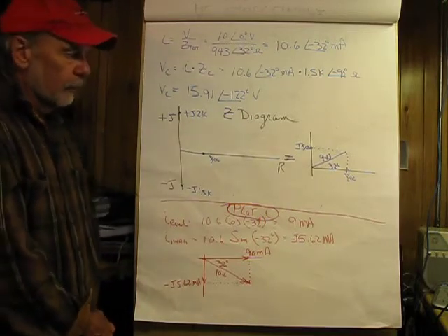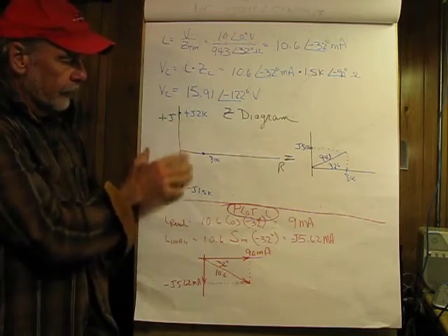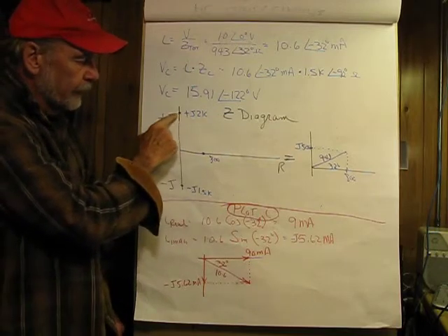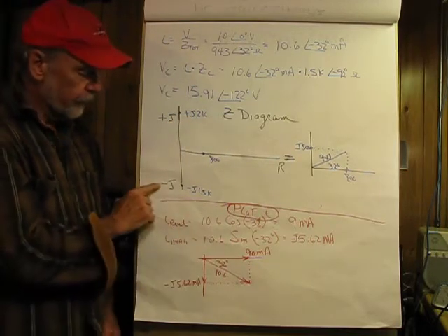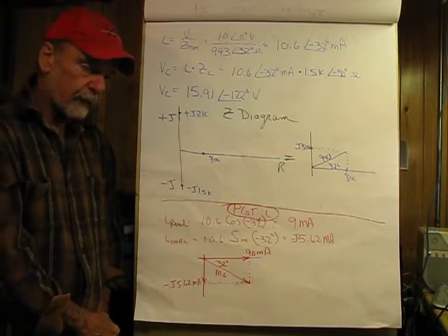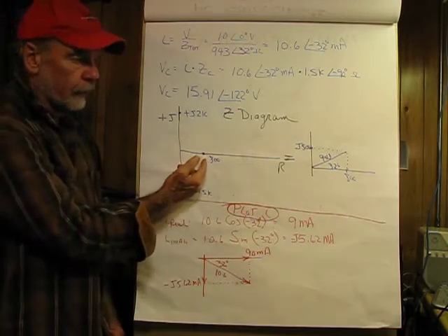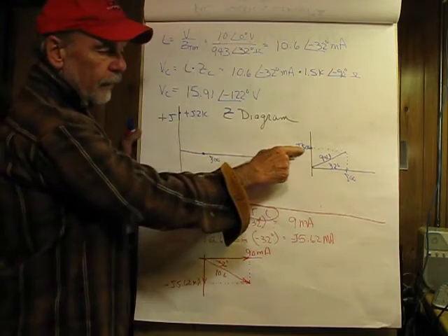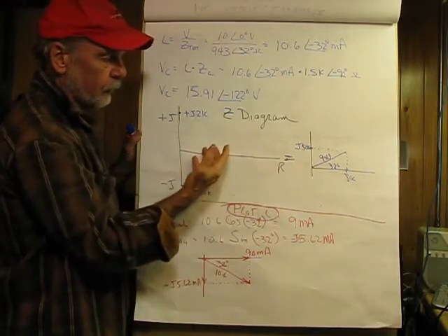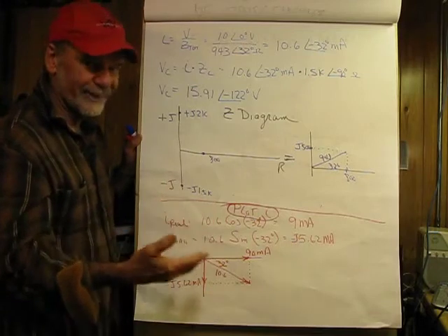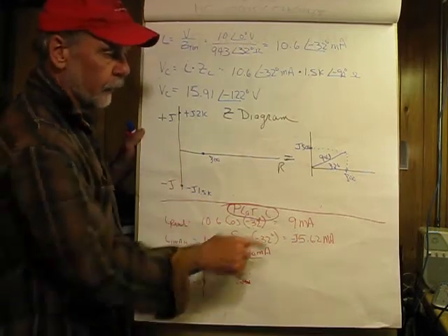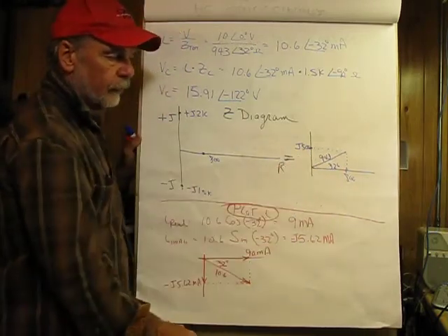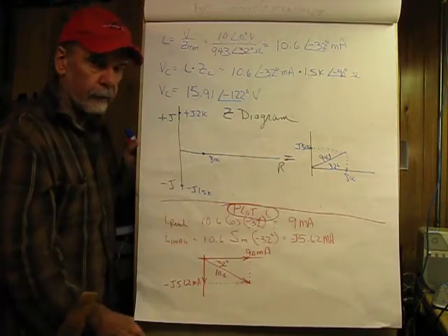So if we look at a Z diagram of this, an impedance diagram, as we're going to see again, this is just a little bit clearer than what I had on the other page. The inductive reactance is sitting up here at j2K, the capacitive reactance is negative j1.5K, and then the resistor here is 800 on the real axis. When we combine the like terms again, we get j500 inductive, because in a series circuit the bigger reactance wins, so to speak, exactly opposite of a parallel circuit. Connect the dots, and the hypotenuse here is going to be 943 ohms, and the angle is going to be 32 degrees.